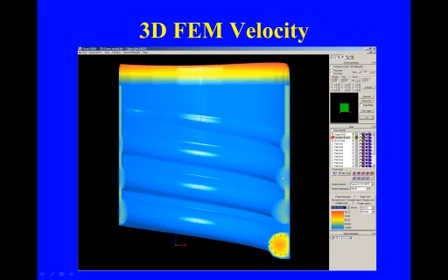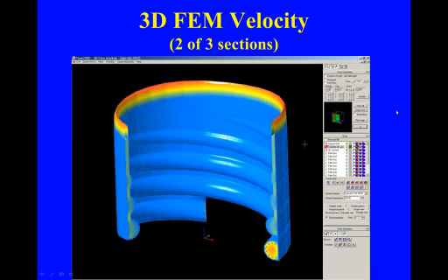Velocity coming in here, blue at the wall is 0 because the velocity is very, very low at the wall. And here we can see the velocity at the exit. We see slight variation in the velocity, a gradual variation, but nothing to indicate that there's going to be a problem with a weld line or the appearance of a line. If we put 2/3 of the flow field together, you can get an idea about the periodicity and how the material flows. There's a slight velocity variation, but like I say, not a lot, nothing to indicate there's a weld line.